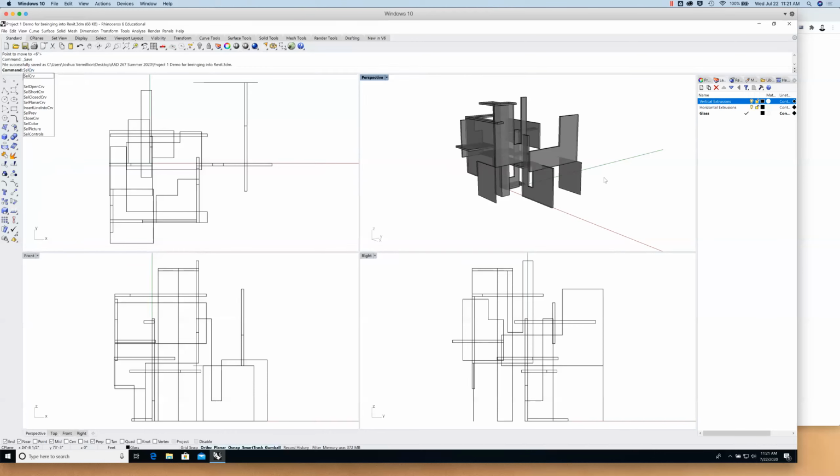There are lots of different geometry types in Rhino, but if you type SEL and then SRF, to select all surfaces, or polysurf, to select all polysurfaces, CRV will select all lines and curves in our drawing. It looks like there's that line that we drew originally. Now that it's selected, I'll just delete it. So now I have just the information that I need to continue to develop in Revit.